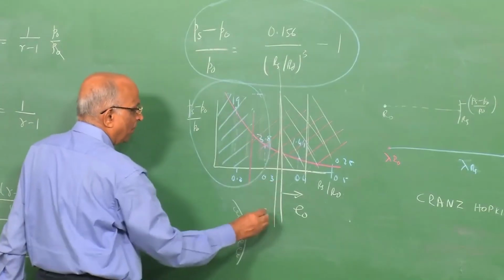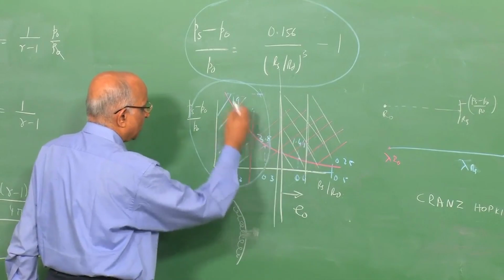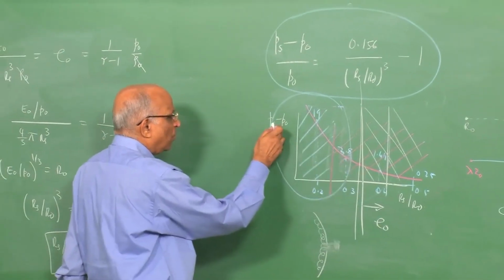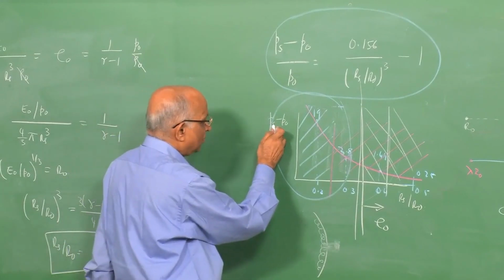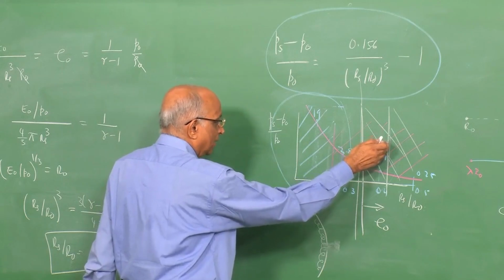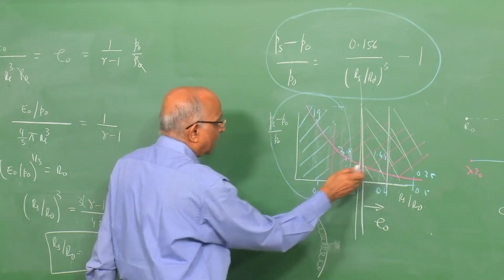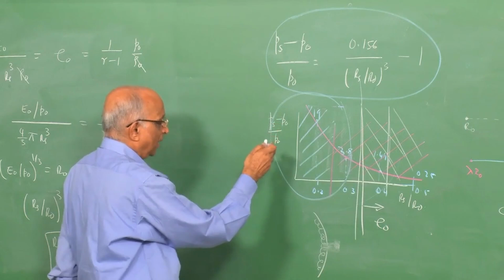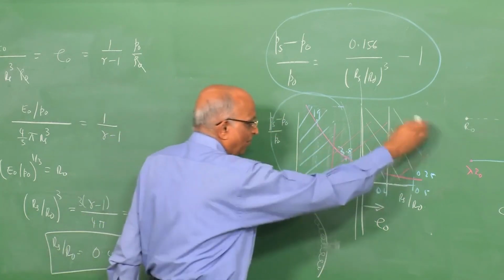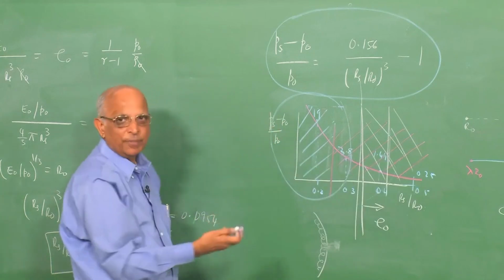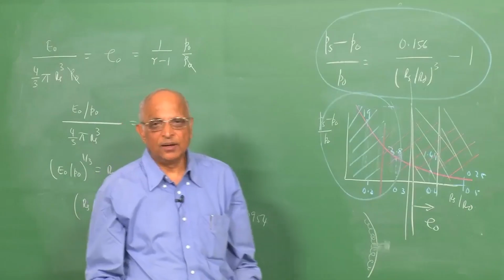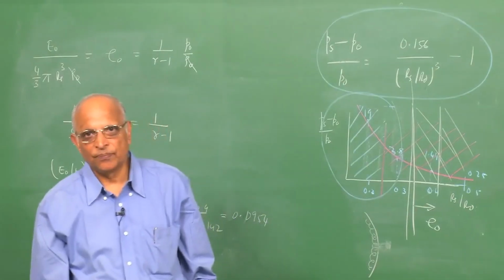Therefore, in the next class, we have looked only at the strong blast region. We would like to take a look at the weak blast region, such that we can have some expressions for it. But the weak blast region is somewhat more difficult, because the initial conditions depend on Mach number. Therefore, we look at the weak region and get the overall picture. That means, in both the strong blast region and the far field region in which the blast wave has decayed, we will try to get the overpressures. In addition, we will also take a look at impulses, and with that we would be done with blast waves. Well, thank you then.